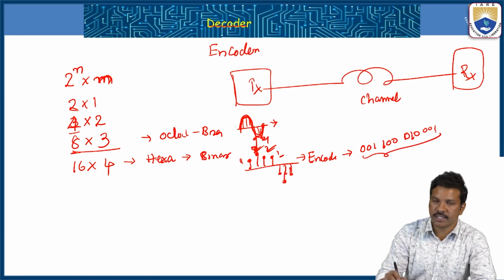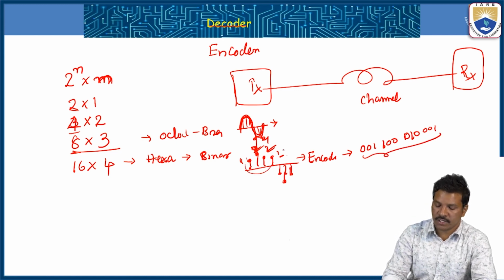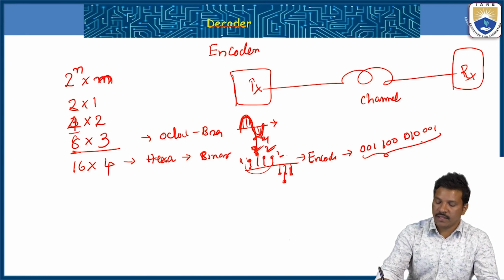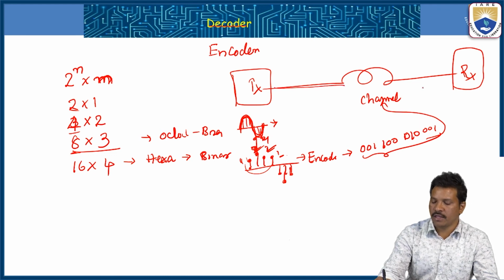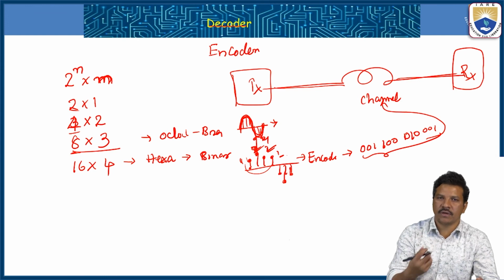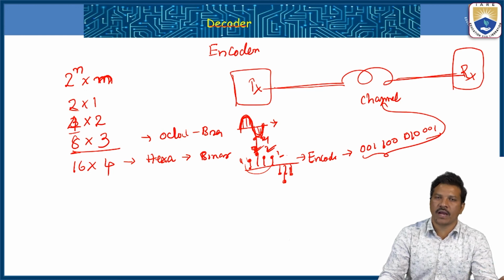This is a series of binary information, the conversion of these decimal numbers of samples by the encoder, and then this binary is given to the channel, passes through the channel, and reaches the receiver. At the receiver, whatever 3-bit binary representation is received can be converted back with the help of a decoder. There we use a 3 to 8 decoder.